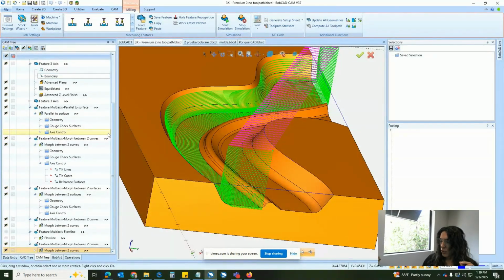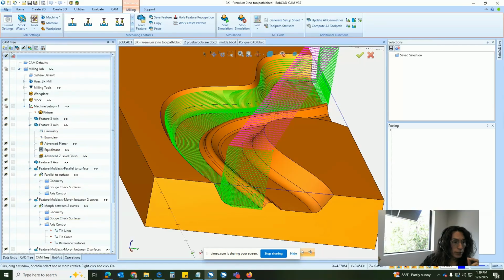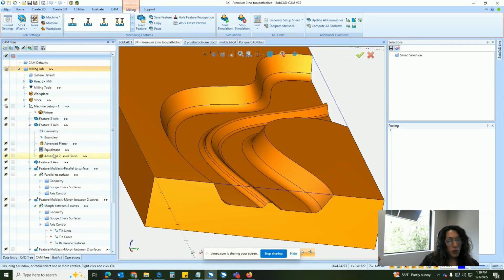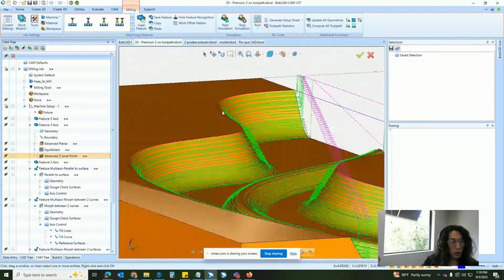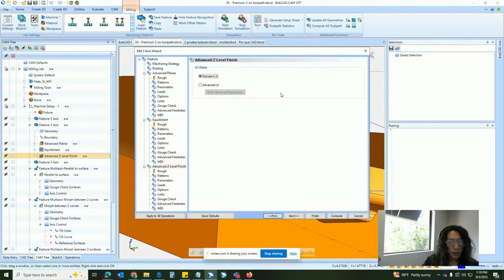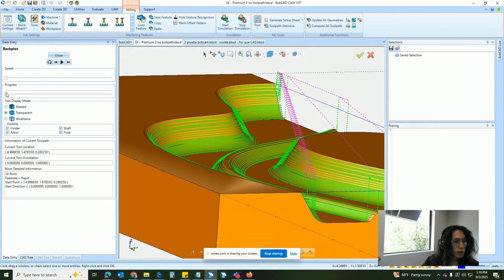Now, are you guys familiar with barrel tools? Okay, barrel tools. That's another big differentiator for our premium toolpaths. So if we were to finish the walls using a Z-level finish operation, we'll probably use a ball end mill, which, let's do a simulation here.